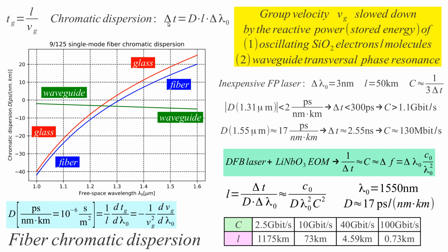So we are going to get our pulses broadened by this delta t, that's equal to the constant of chromatic dispersion times length of fiber times bandwidth of our transmitter. And now this thing is, it is very small indeed. But thinking about the 4 terahertz bandwidth, this thing is very large. So numbers become such that this thing becomes important.